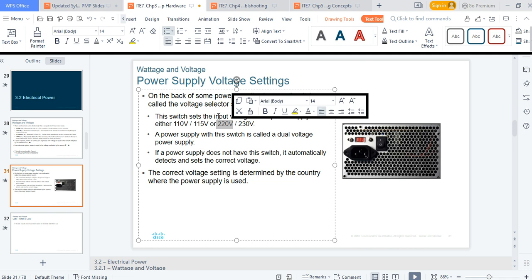So what does the transformer do? It steps down or it steps up. It just transforms the voltage into usable form. When our transformer gets power from the grid, from the power station, it steps it down from maybe 33 kV to 11 kV. Kilo is times 1000. From 11 kV you now have a transformer near your house that steps it down further.